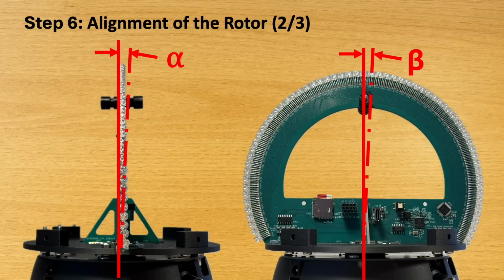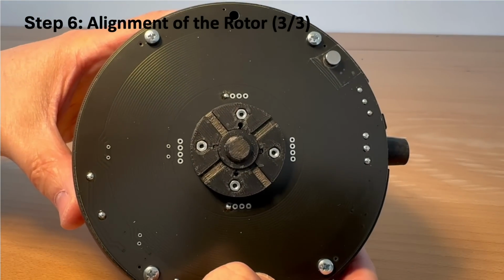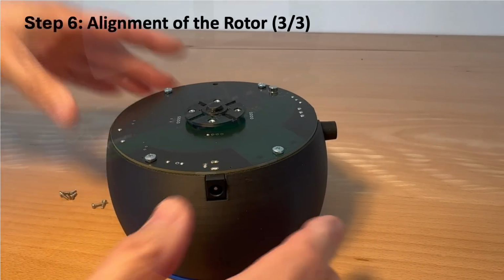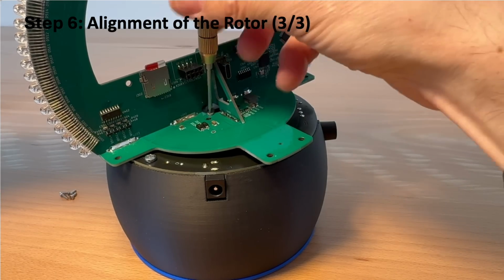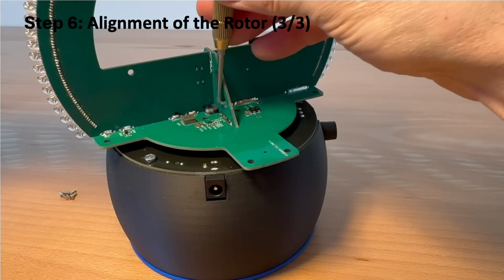The goal of the alignment is to bring the symmetry axis of the LED board into perfect alignment with the motor's axis of rotation. This is done in two steps. First, the angle alpha is adjusted to 0, followed by the adjustment of angle beta. Here you can once again see the four M2 nuts that hold the adjustment screws. When you turn one of these screws, the nuts move up or down, shifting the entire assembly accordingly.